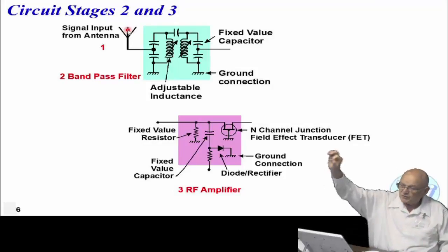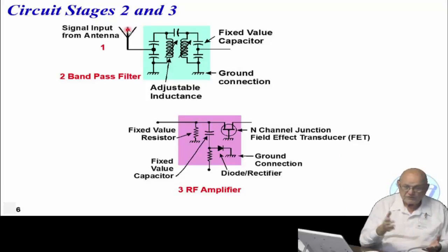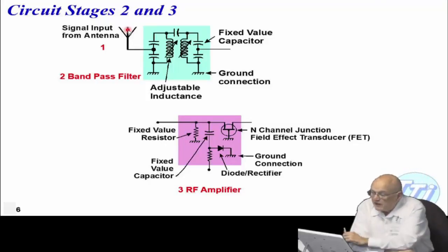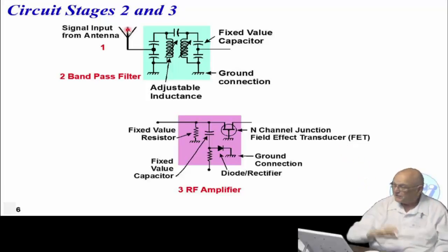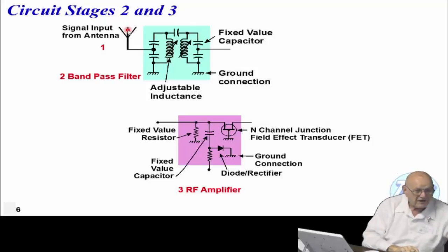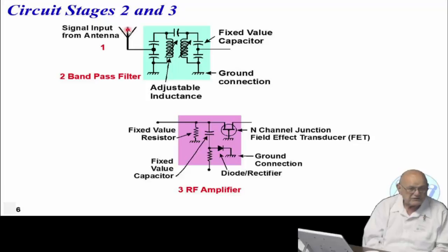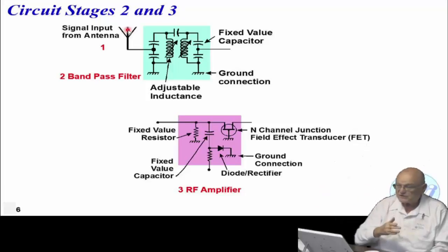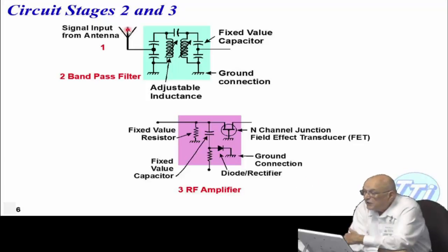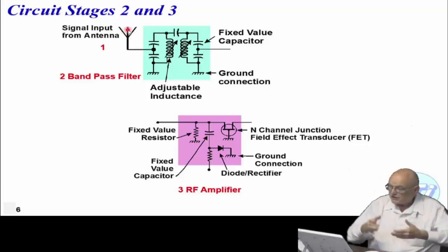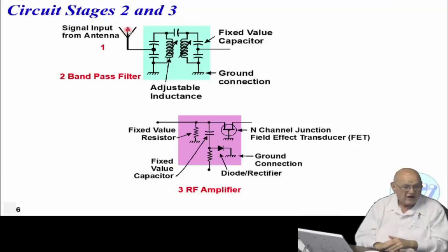Now, you may have noticed that the coaxial cable coming down from the antenna to your TV, or from the dish, is a little coaxial cable. That coaxial cable is 75 ohms, that particular one. And that 75 ohms is actually in an impedance matching circuit that converts the 377 into 75 ohms. And it goes down, and you have a 75 ohm input. That's for maximum power transfer. That's the reason for it. Very important concept you should use. A lot of you have been involved with testing to some degree. The coaxial cable that goes from the oscilloscope, RG58, is 50 ohms. So by convention, 50 ohms is the common impedance used in instrumentation at the higher frequencies.